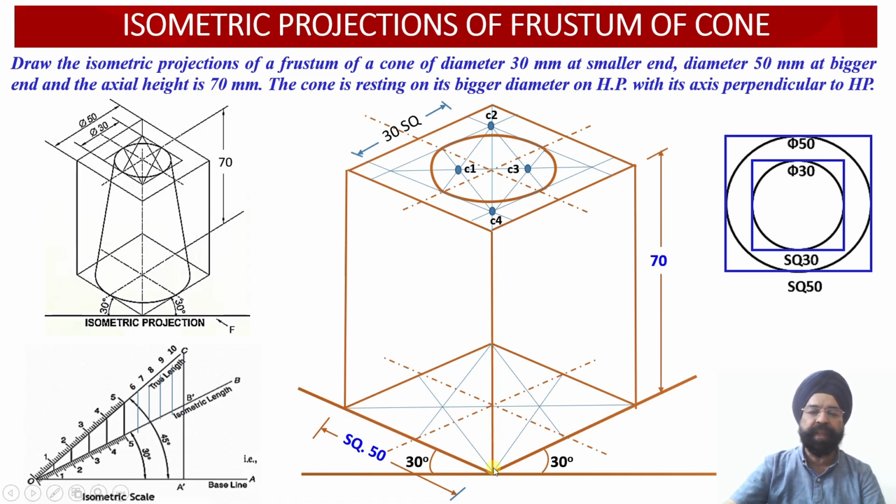from the first end of the minor diagonal, I am going to draw a projector onto the opposite edge on this side. Similarly, from this end of the minor diagonal, another projector will be drawn to the opposite edge midpoint, which will be joining here. Similarly, corresponding to the second end of the minor diagonal, I am going to draw 2 projectors which will be joining the midpoints of the opposite edges.